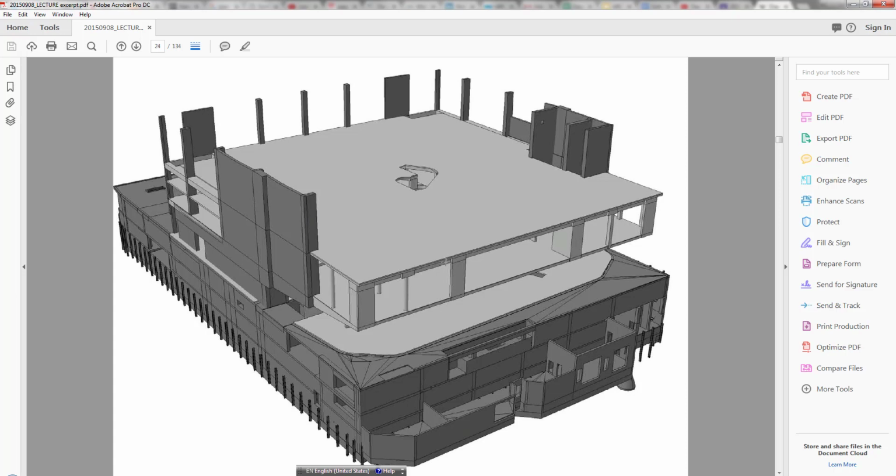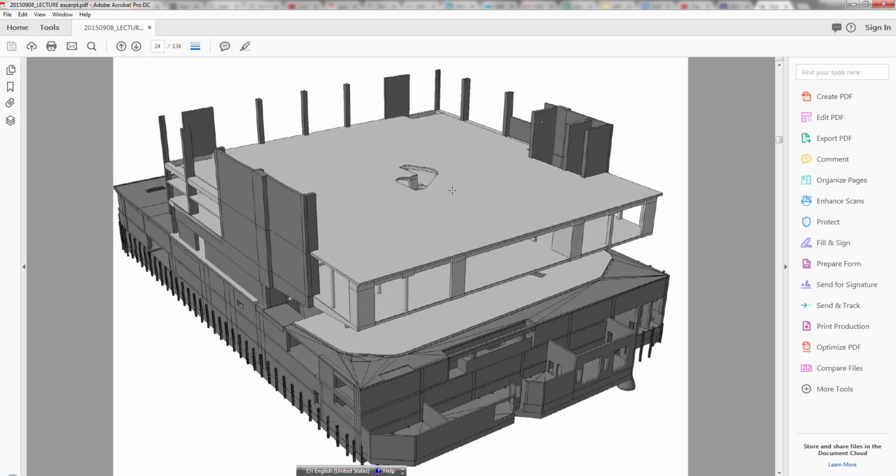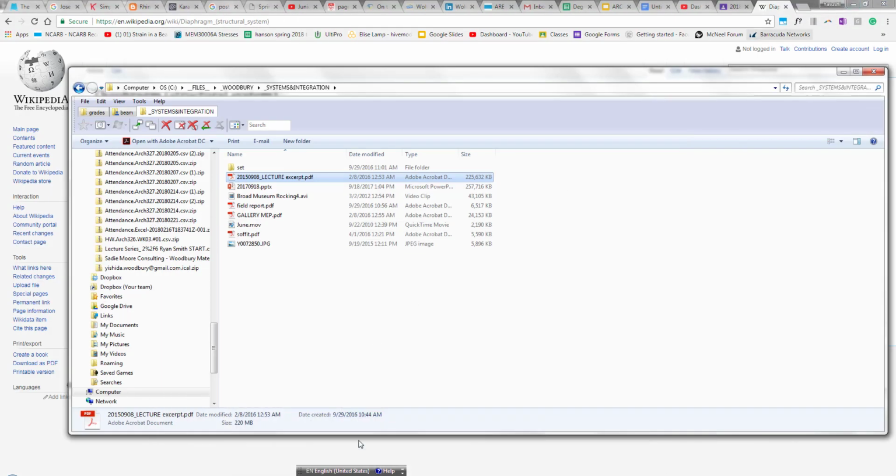And the reason why there's so much concrete wall and columns connecting those two is so that they can work as one diaphragm, which is a peculiar example, so don't worry too much about it. But the idea is that this horizontal thing works as one thing and transmits the force to the shear wall.